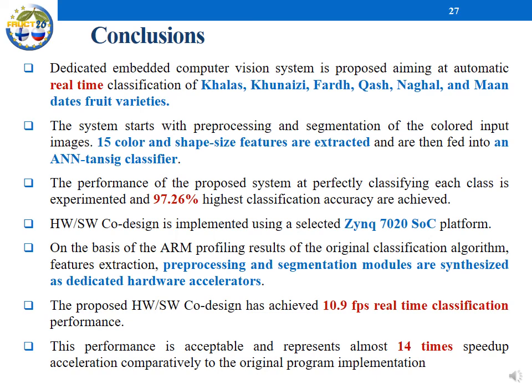Hardware-software co-design is implemented using the selected Zynq 7020 SoC platform on the basis of the ARM profiling results of the original classification algorithm. Feature extraction, preprocessing, and segmentation modules are synthesized as dedicated hardware accelerators. The proposed hardware-software co-design has achieved 10.9 frames per second real-time classification performance. This performance is acceptable and represents almost 14 times speed up acceleration compared to the original program implementation.